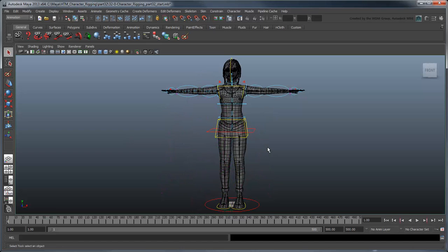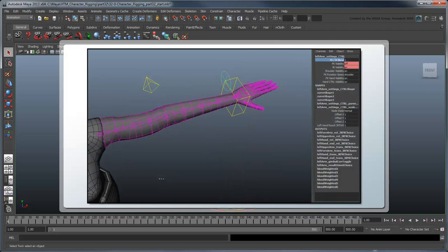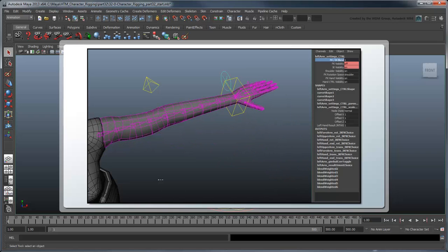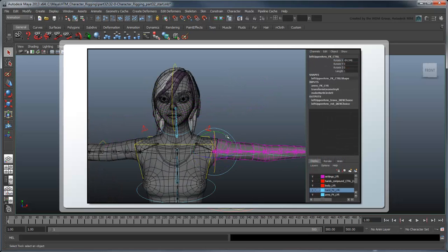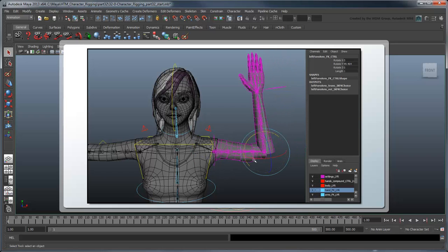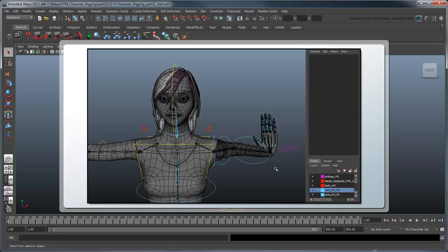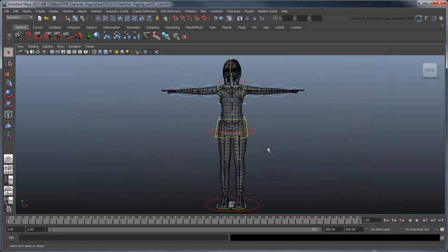However, before you do that, you may want to consider an additional bit of functionality. Although our blend nodes allow us to easily blend from an IK appendage position to an FK one and vice versa, it would be really nice if we could snap one to the other. This would allow us to switch seamlessly from one mode to another in mid-animation without any undesirable pops. In our first appendix series, we'll build a script that adds this IK-FK joint snapping to our rig.